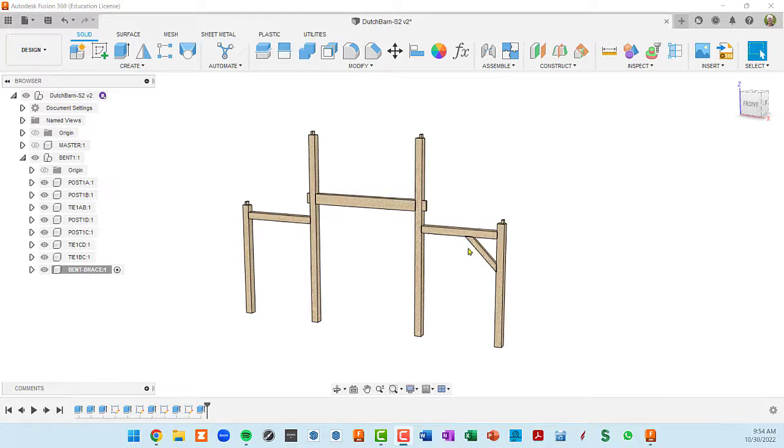So instead of making unique components, we want to make an identical copy of a component, and then if we change one, we end up changing all of them. So that's what you see with this :1 at the end of all of these components. It's saying that this is the first instance of this component, and each one of them just have a 1 on it. Now when we start reproducing these braces, you'll see that they'll have 2, 3, 4, etc.